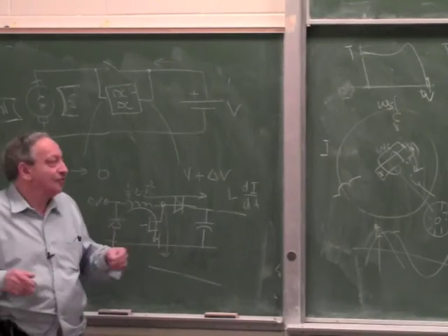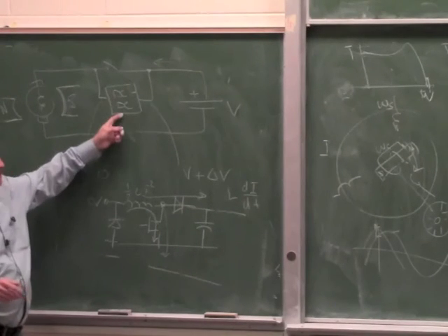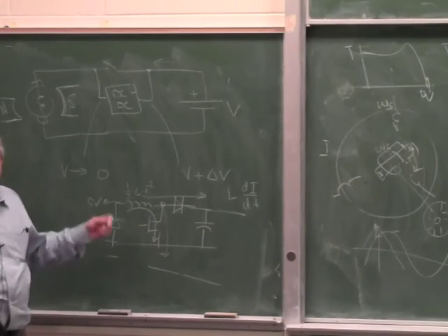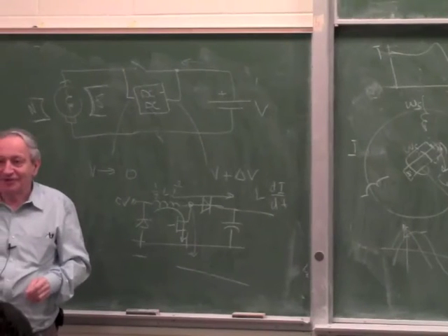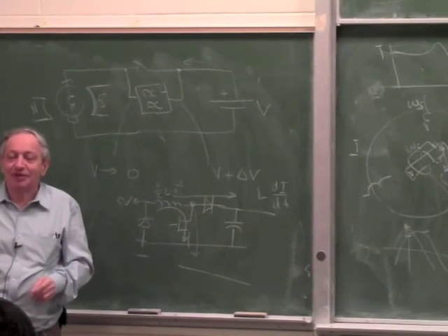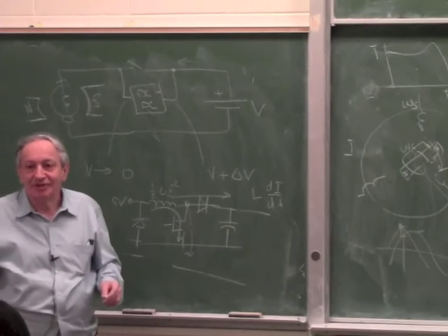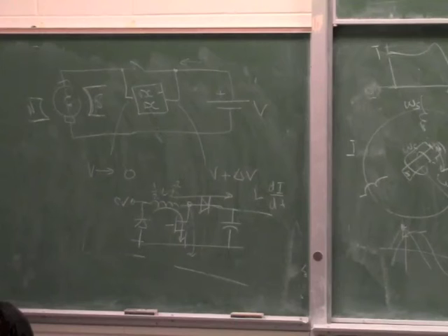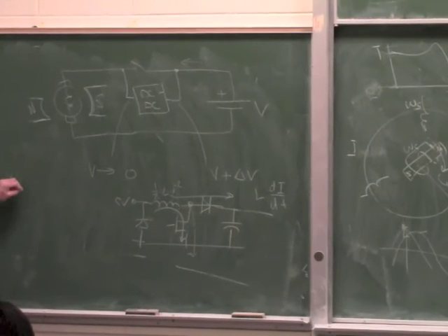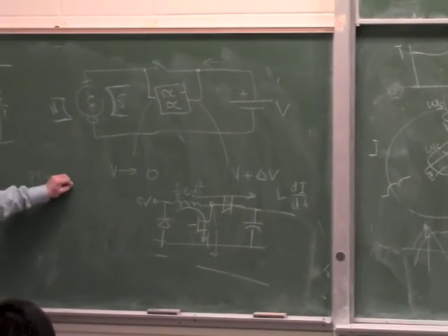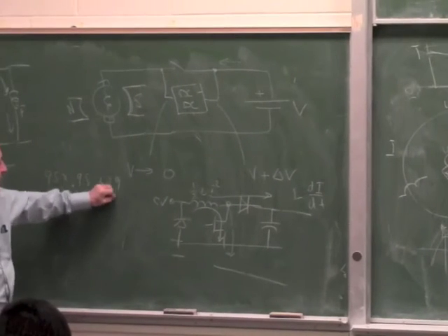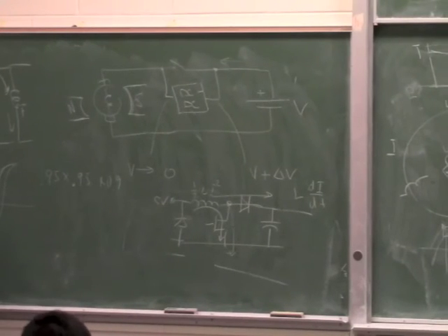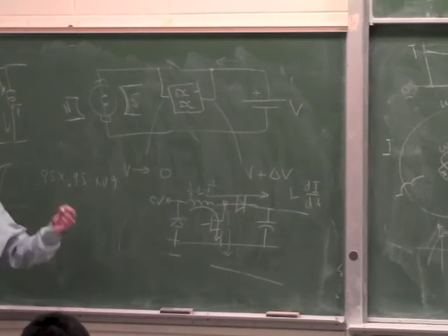Because if you really do a very good job with a DC to DC, this DC to DC is like 95% efficient. A generator is like 95% efficient. So 95 times 95 times battery is 90% efficient. So if you really do the math, even for an electric bike which is well designed, you can get 0.95 times 0.95 times 0.9, which is the battery. So you get overall maybe 80%, but it's not bad at all. So most of the energy does recover to the battery.